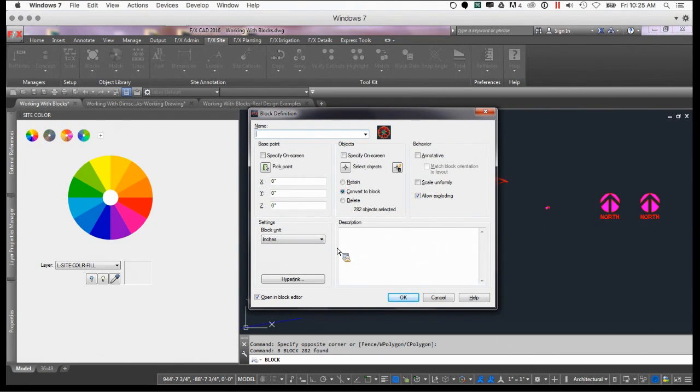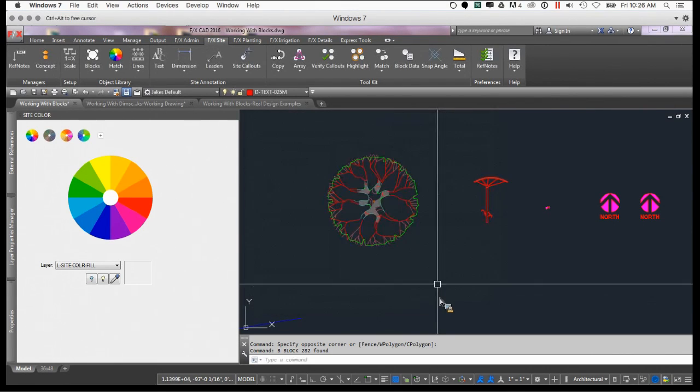How is that block actually drawn, in what units? Because as you insert these blocks into specific drawings, it actually takes that unit setting and applies it. So we've all dealt with this, if we've inserted something and it comes in way too big or way too small, it's basically because the unit setting on that and that conversion, or however big that actual block was, wasn't set correctly. So all things to think about, but we're actually going to step back and show you how